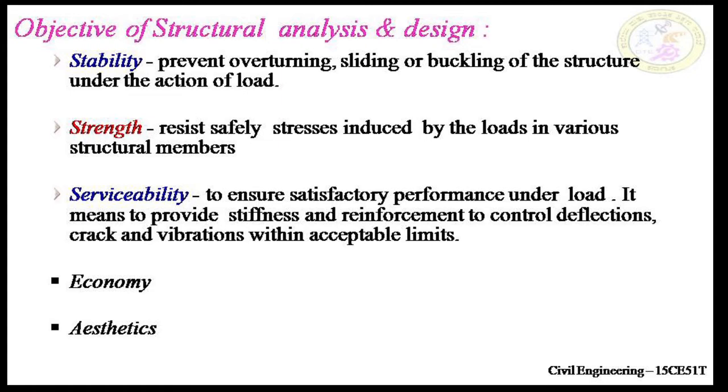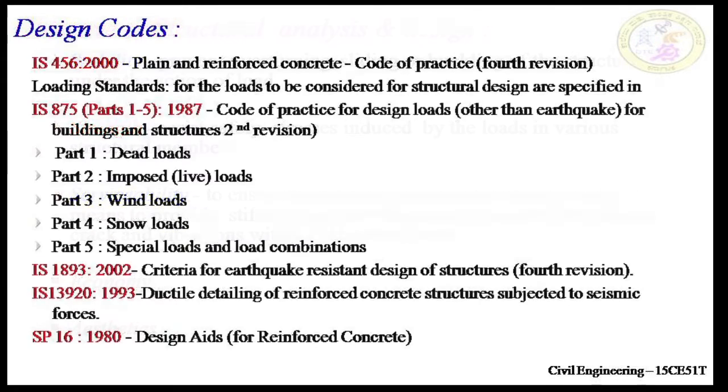Serviceability is to ensure satisfactory performance under the load and to control deflection, cracks and vibrations within the acceptable limits as specified in the code. Together with this, it should be of reasonable cost and also give a good appearance. These were a few objectives of structural analysis and design.